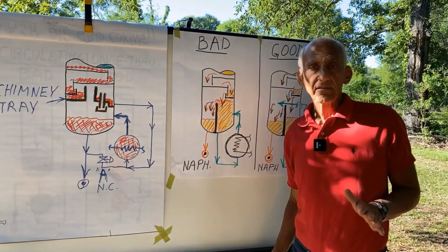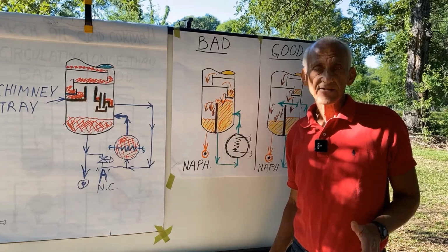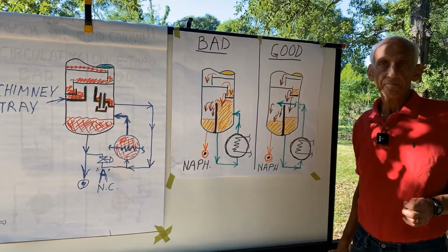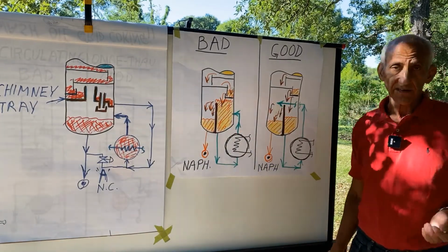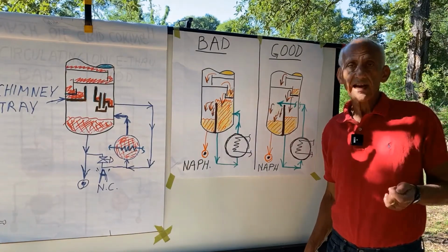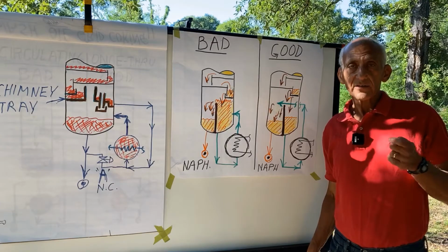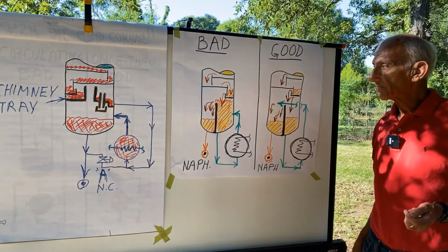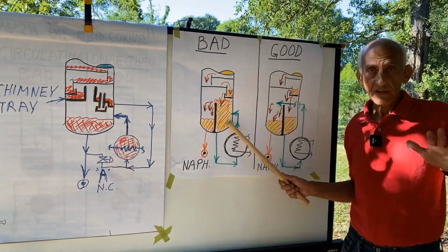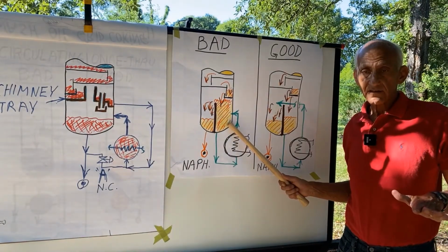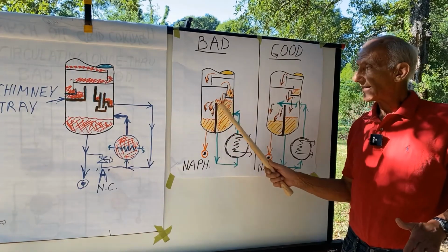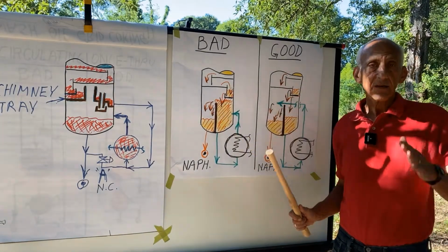But how about the very common distillation towers that have vertical baffles in the bottom of the tower? This is an extremely common design. It's done this way all over the world. Take a look at your towers that use a vertical baffle in the bottom of the tower. The liquid, of course, comes off of the bottom tray and falls into the cold side, the cold half of the bottom of the tower, which is segregated into the cold side and the hot side by the vertical baffle.